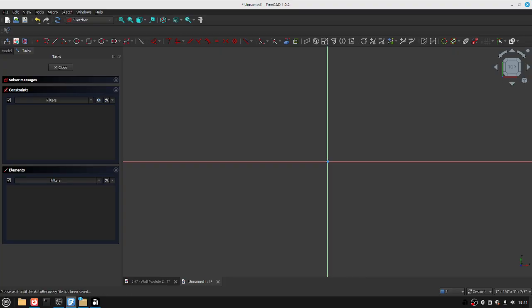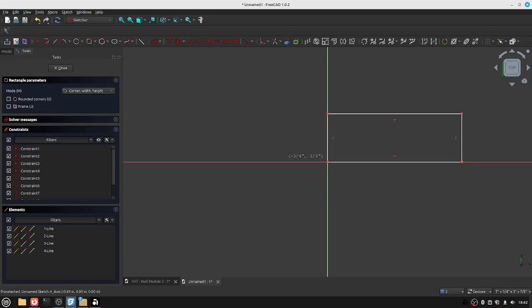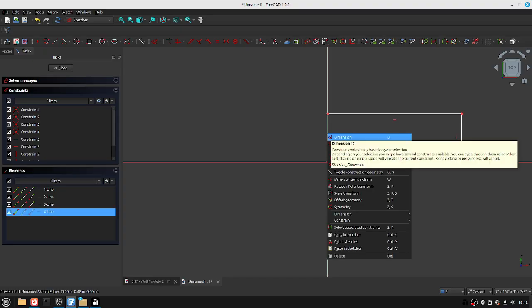And you have to simply think about constructive geometry. What am I going to do? For me, the simplest thing would be I'll draw a bottom plate and I'll make 3 studs on top of that. Let's do that. And then you got to cap it with a top plate. But I would do it in the following way. So start at the origin. I would do this. So this is for real now. I'm going to click on that. And I'm going to click dimension.